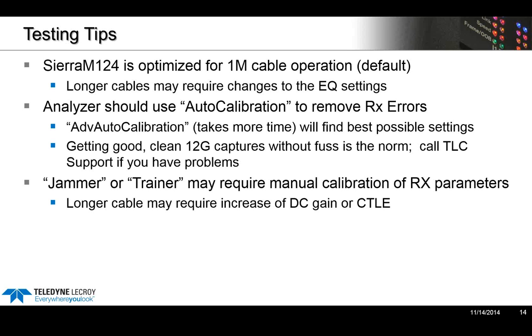So my second bullet point here, the analyzer should use auto-calibration to remove RX errors. Well, that primarily refers to our tuning between the signal that we are sniffing and to make sure that we have a good clean capture. And we have an auto-calibration feature.